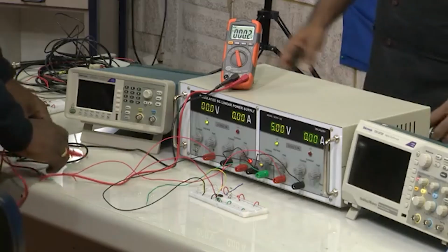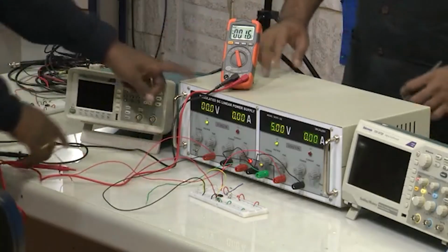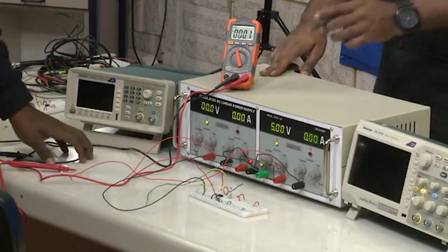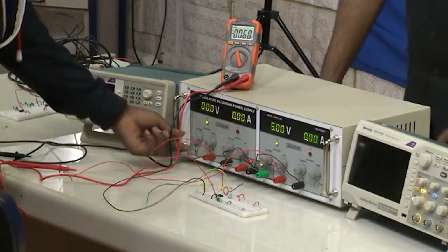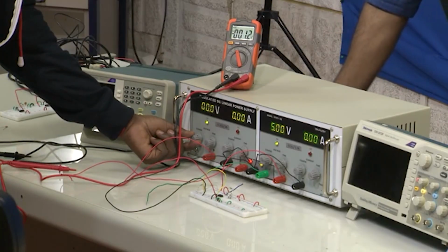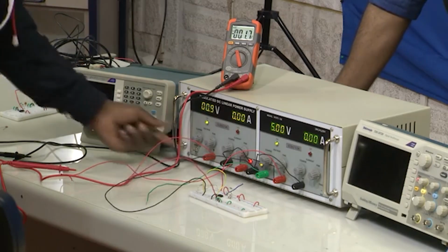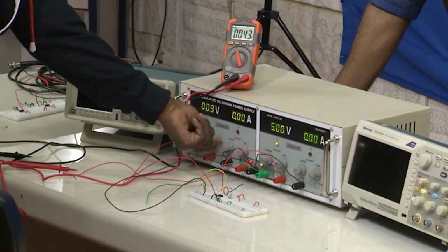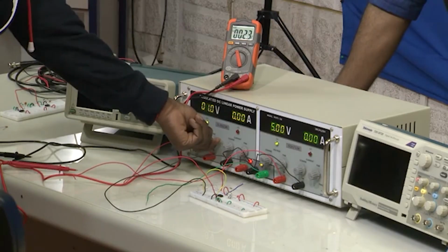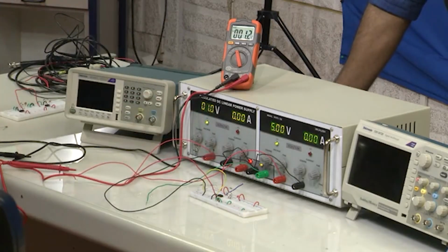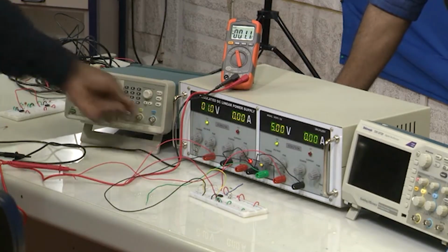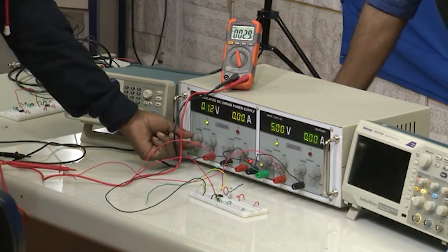Now, let us apply different voltages through the power supply to the non inverting terminal. So, can you please apply? Now, you see he is increasing from 0 slowly, 1.7, 1.9, and we see there is no glow in the LED, right. That means that your inverting terminal is still high, which is obvious because the inverting terminal is 2.5 volts, non inverting terminal is 1 volt. So, still V in is less than V ref. When V in will be greater than V ref, then only we can see the output plus 5 volts.